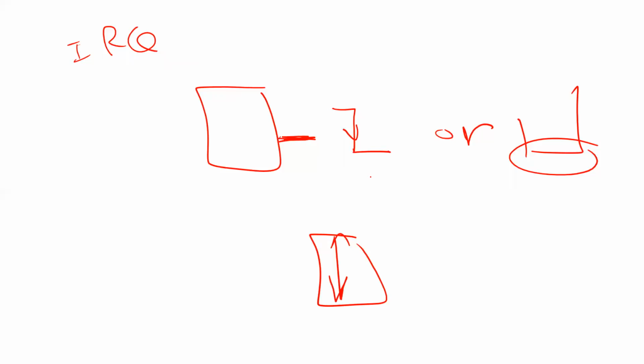Someone can ask me where this falling edge is going to come from. It can come from a switch, as I explained last time, and as we are going to do in the lab today. Every time I press the push button, you actually trigger an interrupt. This is one way to do it. Another way, it may come from a sensor here. This sensor is sensing something, and when someone is cutting the infrared light, or there is a fire alarm or whatever, there will be a falling edge here.